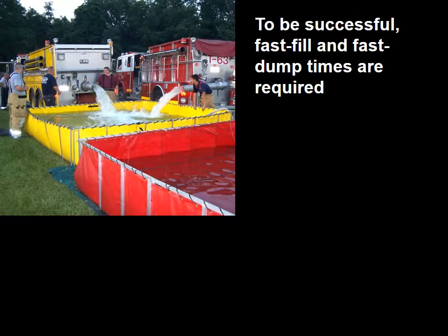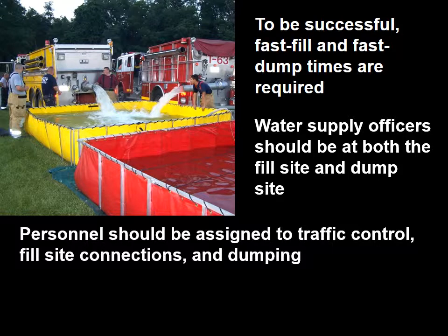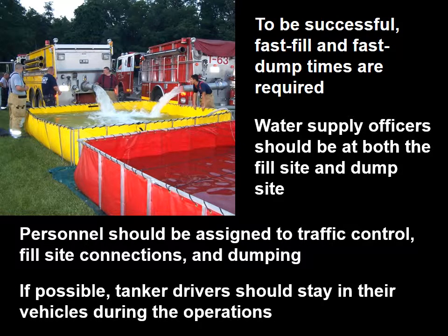To be successful, fast fill and fast dump times are required. Water supply officers should be at both the fill site and dump site. Personnel should be assigned to traffic control, fill site connections, and dumping. If possible, tanker drivers should stay with their vehicles during this operation.